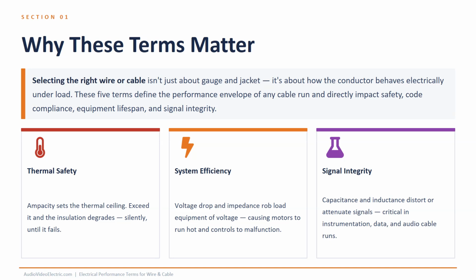Ampacity determines thermal safety. Exceed it, and insulation silently degrades until failure. Voltage drop and impedance reduce system efficiency, causing equipment like motors to run hot and controls to malfunction. Capacitance and inductance are crucial for signal integrity, especially in instrumentation, data, and audio applications.